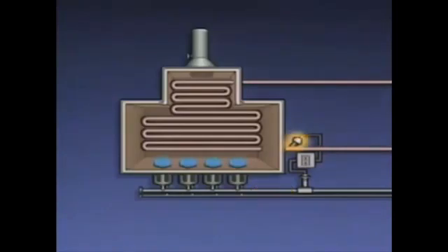There's a thermocouple to measure the outlet temperature, a temperature controller, and a fuel flow control valve. During operation, there's a desired outlet temperature or set point. Deviations from set point trigger control actions.